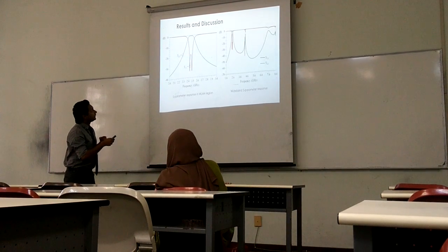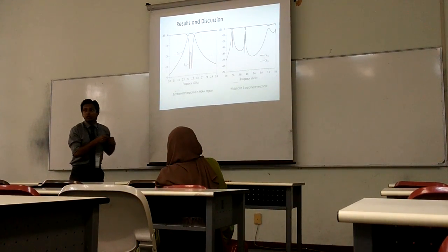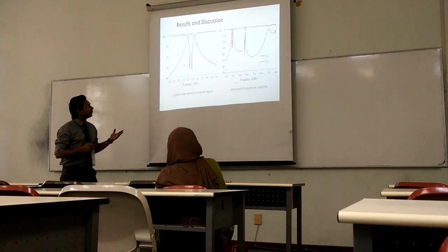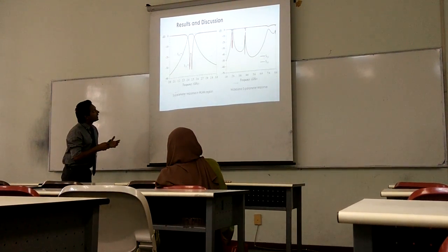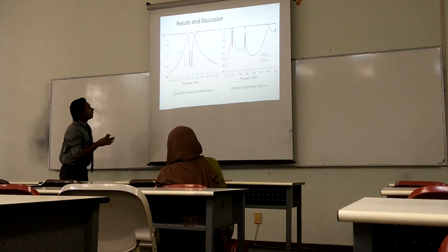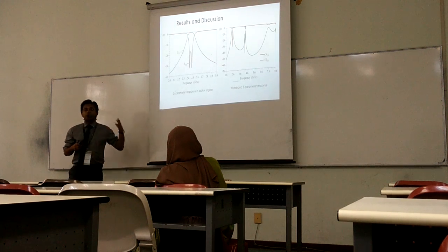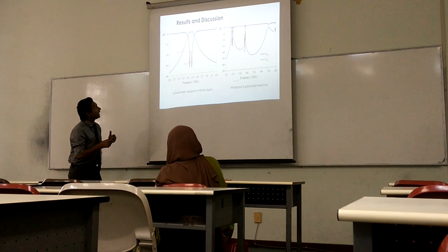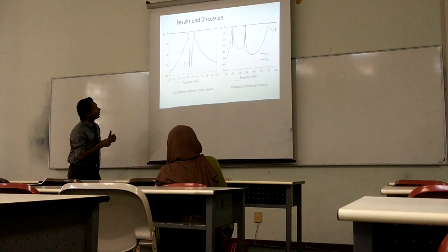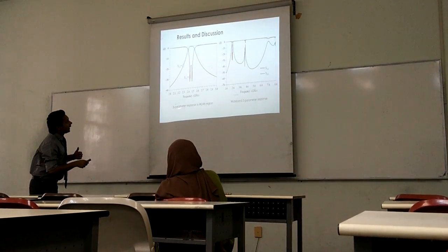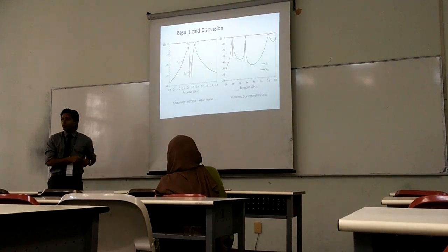I mean, in this S11 and in S21, both ripple. But in our case, we have proposed something like a quasi-Chebyshev response. So for S11, we have a second order response, like this, with a ripple. But on the top, there's a maximally flat response, which ensures a consistent level of insertion loss, as we have mentioned here. So from here, you can see it's a consistent level of insertion loss that mostly covers this 100 megahertz bandwidth. So this is the S parameter response in the WLAN region.